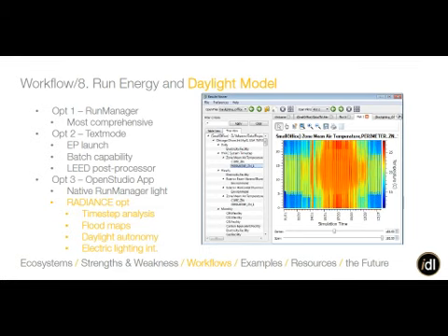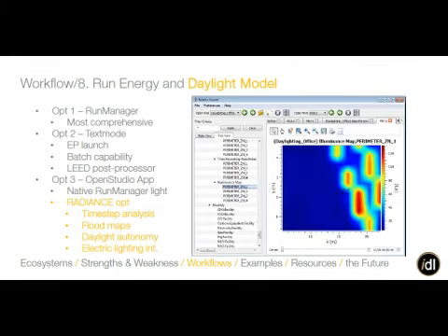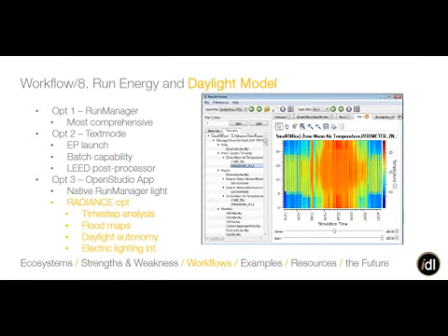So the purpose of this is to generate abstract artwork? Not quite, right? Half of the battle in energy modeling is getting it to output data. The other half, which is potentially more important, is how to interpret this data for design, right? And this is just one snapshot of the entire year. Sometimes these flood maps can be more important in terms of this would be mean level of luminance for that analysis grid throughout the entire year.